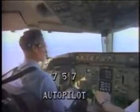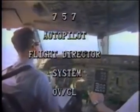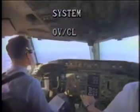Flight Director System, or AFDS, provides the pilots with accurate, reliable control and displays during all phases of flight. This is accomplished using a triple-channel system to achieve a fail-operational autoland capability certified to Category 3B conditions.